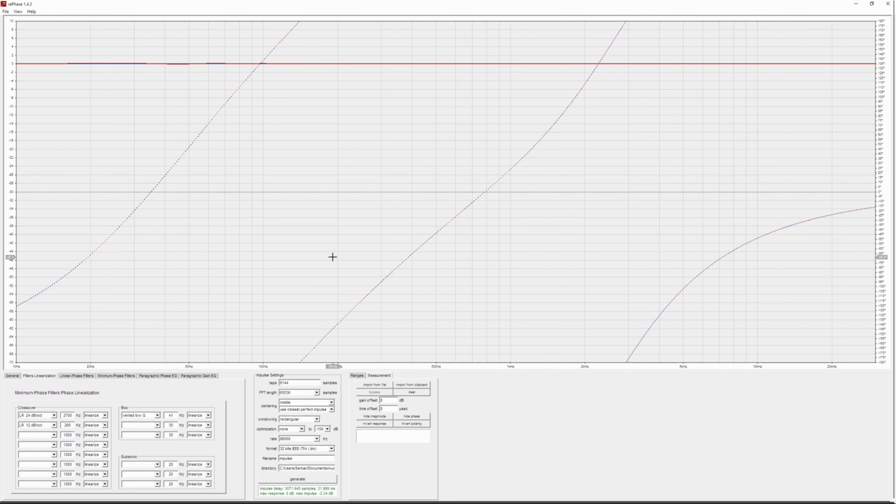So the box filters work too low down the frequency band for 1024 taps to ever be sufficient. It's an additional advantage of using biquads. You can easily apply this filter with biquads to the very same miniDSP. Or in my case, I use a balanced 2x4, the very first model of miniDSP, and it doesn't even accept FIR filters, only biquads.